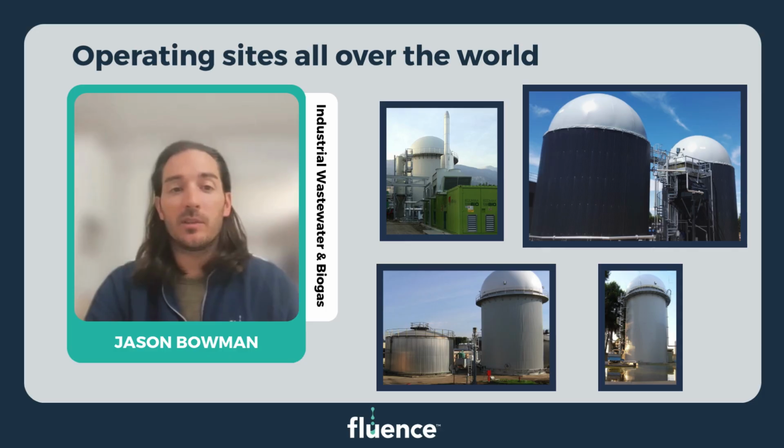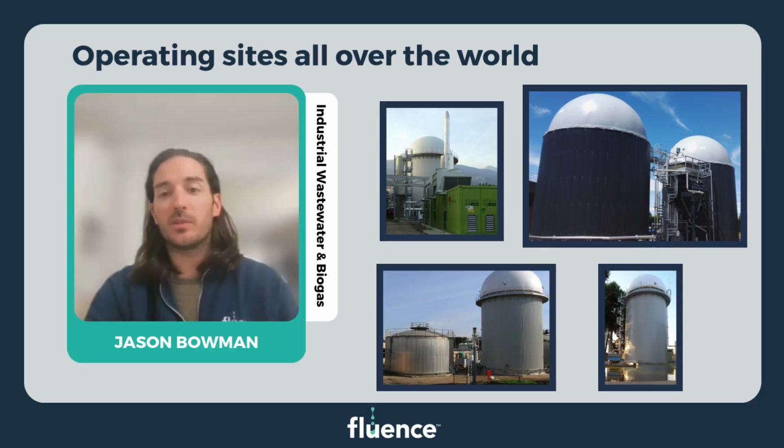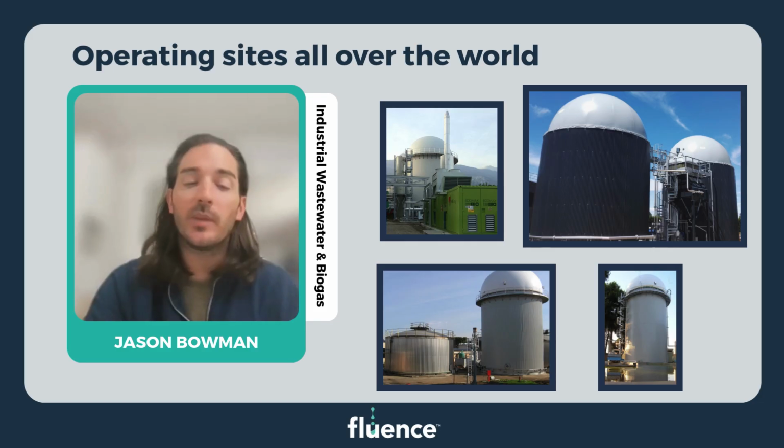And these EFC reactors often have diameters well under 20 feet. These systems are capable of reducing organic loads by well over 90%. I would say 80 to 90% is kind of the sweet spot, but there are some systems that can achieve higher than 90%. So these are a great method for providing stable, trusted wastewater treatment prior to POTW discharge.